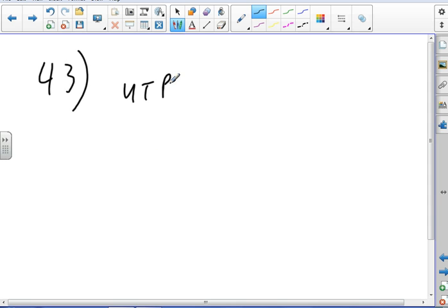The upper trip point is RF2, 2.9K, I'm looking on page 862, divided by 3.9K plus 2.9K, times 5 volts. So that should be the upper trip point.